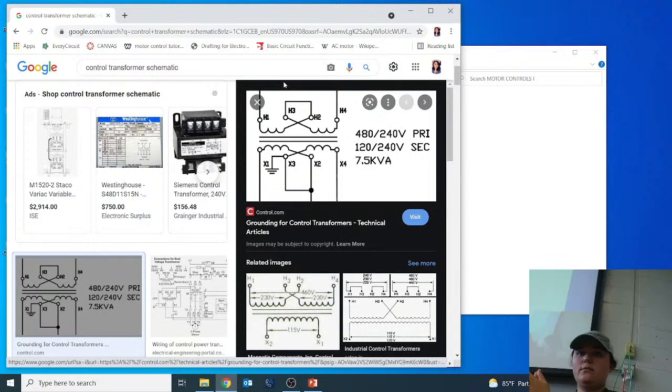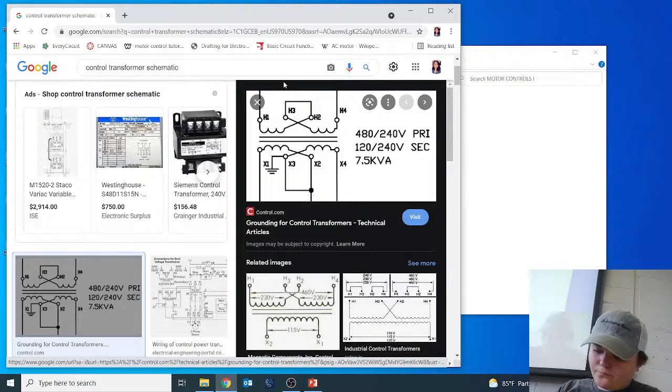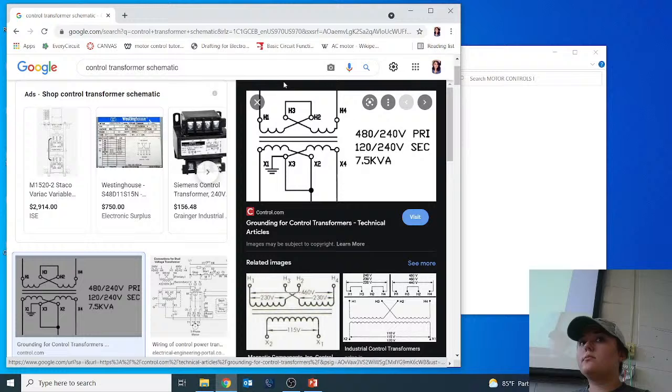So 2 to 1, and that's what kind of transformer? Step up or step down? Step down. So you're going from 2 to 1. It's a step down, correct? Right? Caden, are you getting this? Okay. So a turns ratio, whatever number is in front, determines if it's a step up or a step down. So if it's a 1 to 2, what would it be? Step up. Cool. Now are we getting it? Kind of clicking? Okay, cool. And the reason that you need them in parallel, if you're coming from 240 to 120, what is 240 divided by 2? 120. Okay, cool.